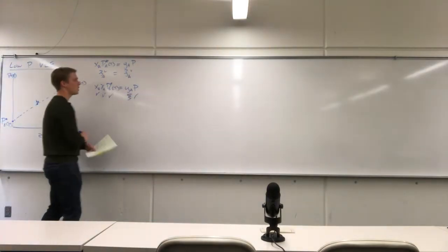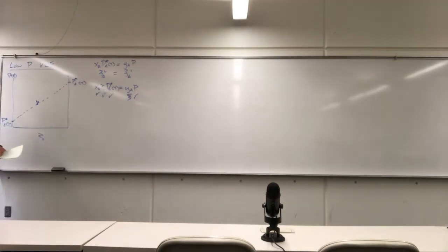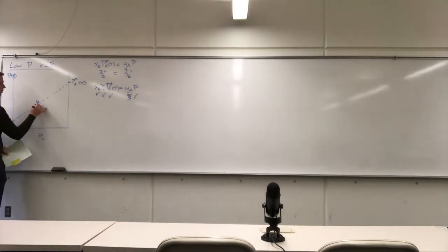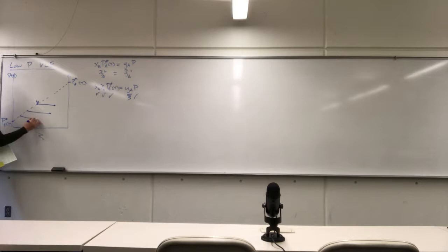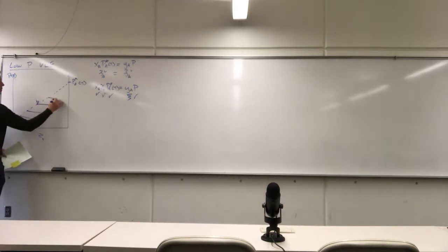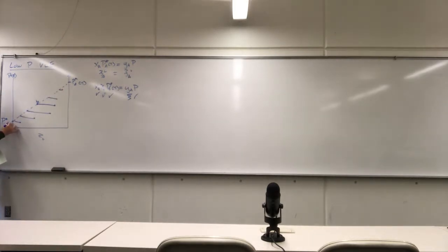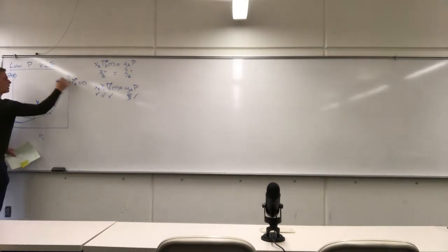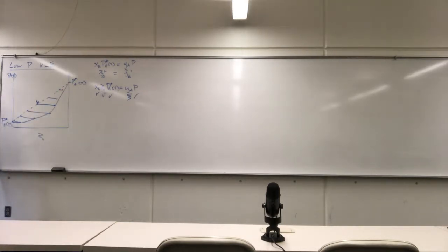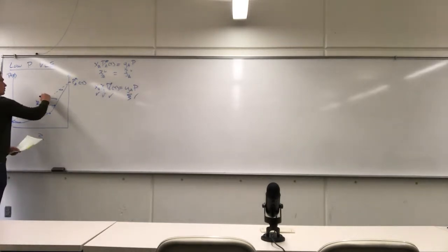Which means that we can directly solve for the vapor mole fraction, which allows us then to draw a line over here, and we can construct a dew curve by repeating this process over and over again, and then we simply connect the dots and we have our dew curve. Will it be a bubble curve? This is the bubble curve here.